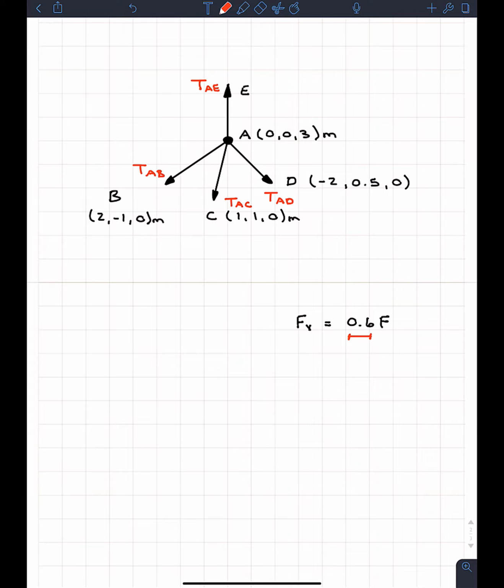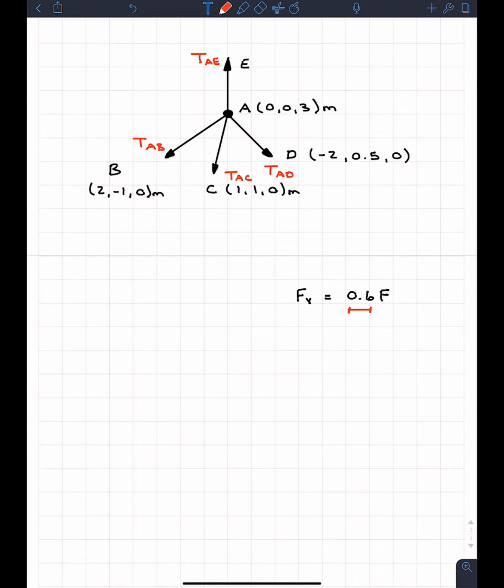And well, how do we get those in 3D? And the answer is actually going to be unit vectors. Because what a unit vector does, and I'm just going to switch to black for a second. So if we had a unit vector of a force, and let's just say for fun, I'm just going to write random numbers down, but it's 0.6i minus 0.7j plus 0.1k. And again, this is probably not a unit vector. The magnitude is probably not equal to 1. I'm just putting random numbers down.